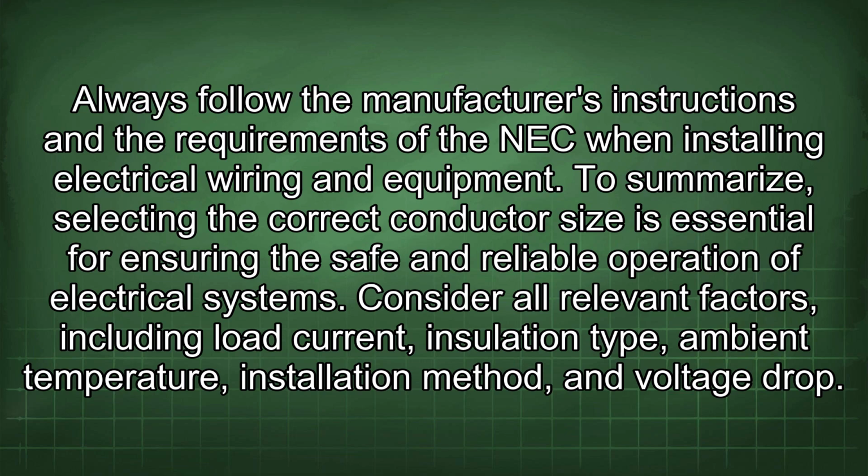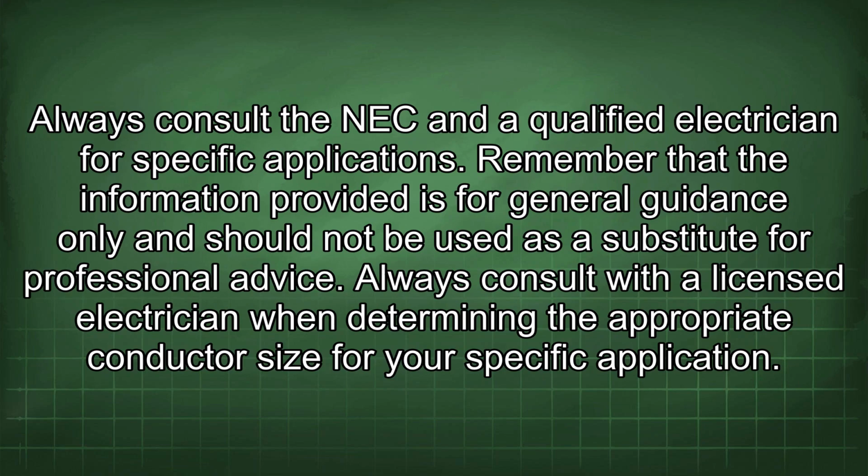To summarize, selecting the correct conductor size is essential for ensuring the safe and reliable operation of electrical systems. Consider all relevant factors, including load current, insulation type, ambient temperature, installation method, and voltage drop. Always consult the NEC and a qualified electrician for specific applications.